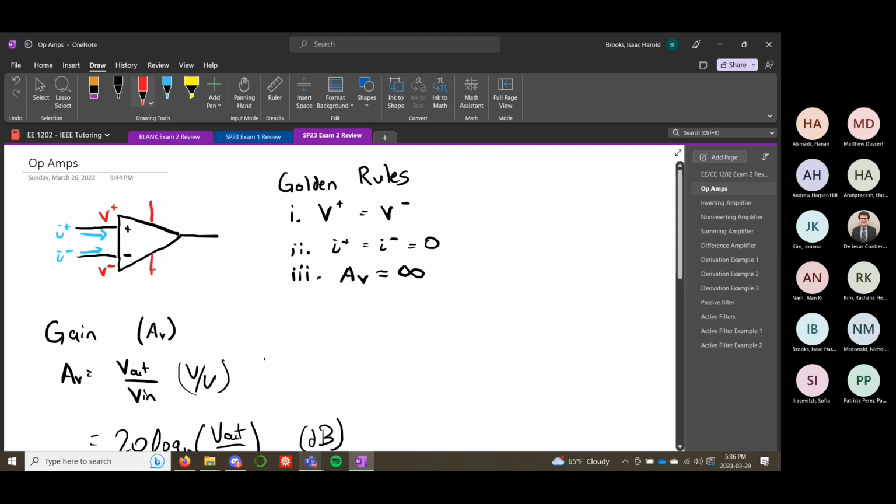There's a couple of other inputs. There's usually a VDD, VSS or something, some kind of positive and negative supply rail. You don't really see this in our schematics, but when you're building the circuit, this is basically going to say the maximum voltage and the minimum voltage that the op amp can output. So these things aren't magic. They can't just give you any voltage. You have to supply it a voltage, and it'll amplify a signal to somewhere between the maximum and the minimum voltages.